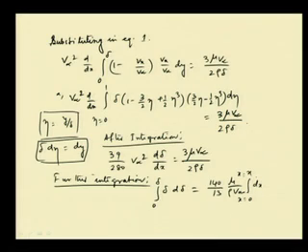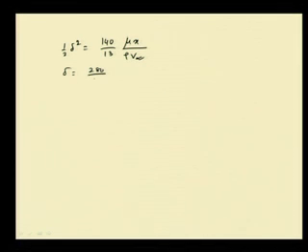So, at x equal to 0, delta equal to 0, and at x equal to x, delta is equal to delta. Okay. So, based on that, if we do the integration, what we get is half of delta square becoming 140 by 13 mu x by rho into V infinity. So, this finally gives us that delta is equal to 280 by 13 into mu into x by rho into V infinity whole to the power half.